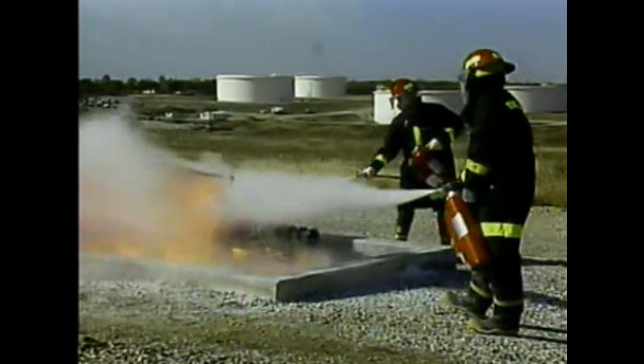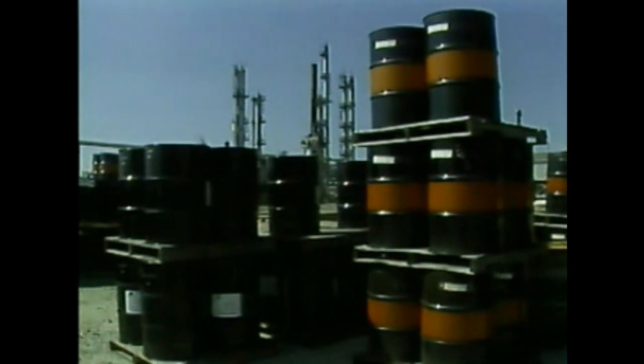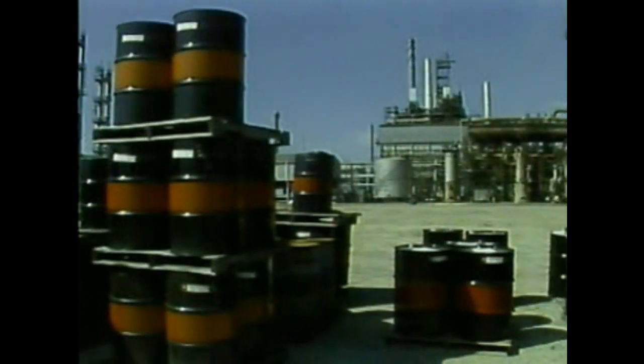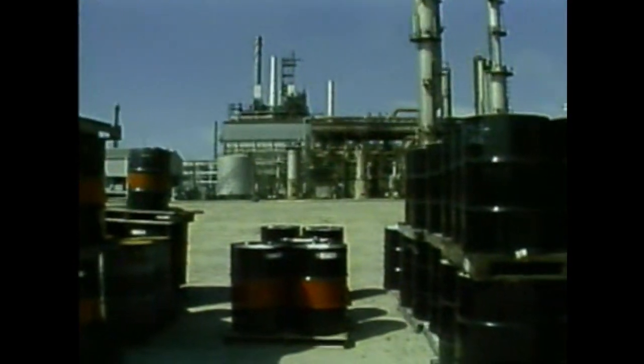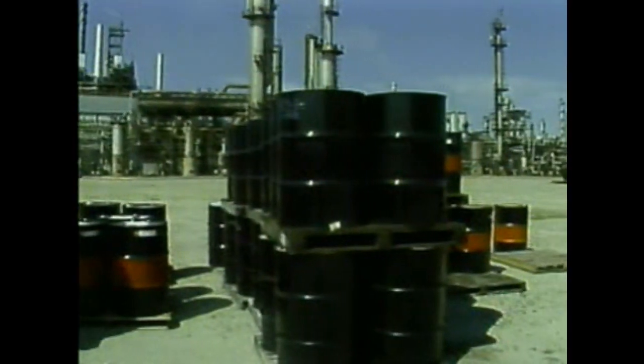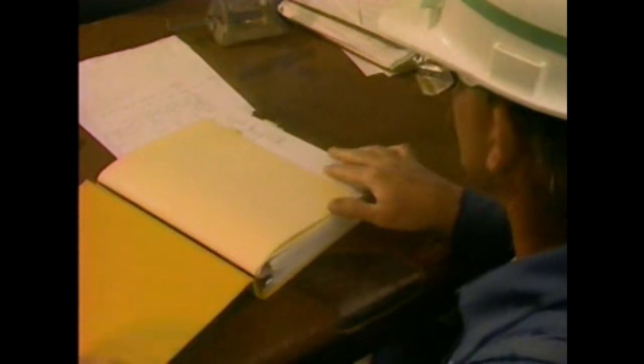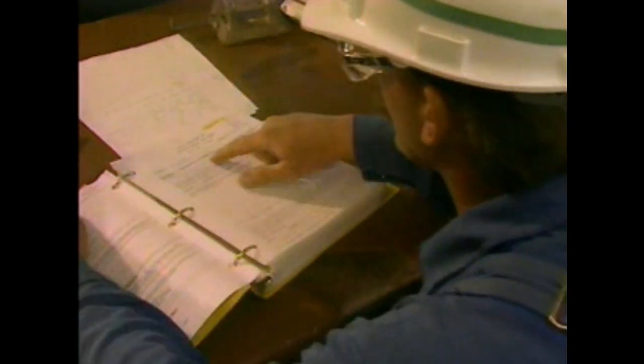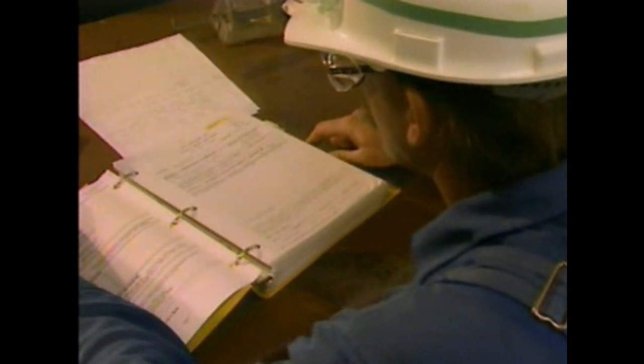In this part, we'll examine strategies for responding to emergencies such as unintentional chemical spills and releases and accidental fires. An important step in chemical safety is prevention. You should know the hazards of the chemicals that are being used or stored in your area. If you're unfamiliar with a chemical, you should always check the MSDS to find out what safe handling procedures are necessary and what protective gear you need.